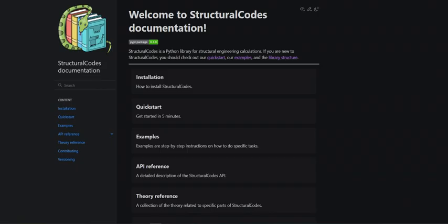And why are we doing that? Well, when we do this, we can quite easily swap the material with another material, and then the geometry and furthermore the section will treat it as just another material, and it will ask this material for relevant properties.